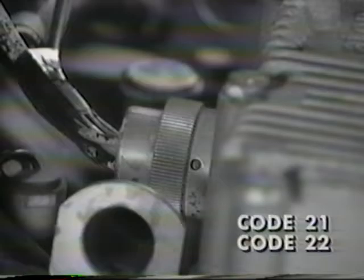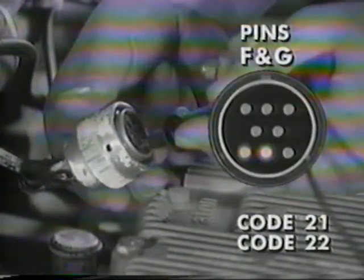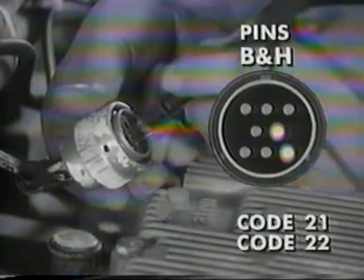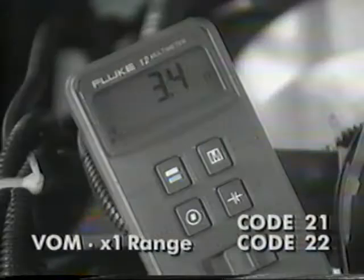Disconnect the torque converter harness connector from the front of the shift bar cover. Now, probe the pins on the harness. For code 21, probe pins F and G. For code 22, probe pins B and H. In either case, the reading must be from 2.5 to 4 ohms. If it's below that, it indicates there's a short in the coil. If it's above that, it's open. There's no continuity.